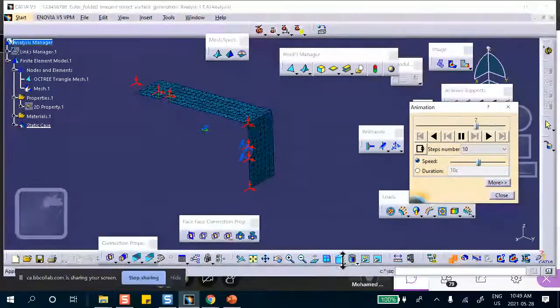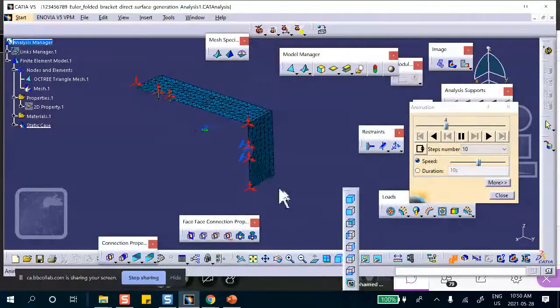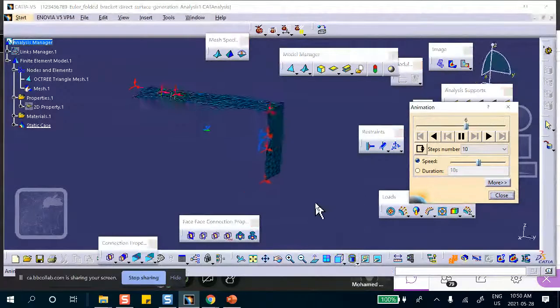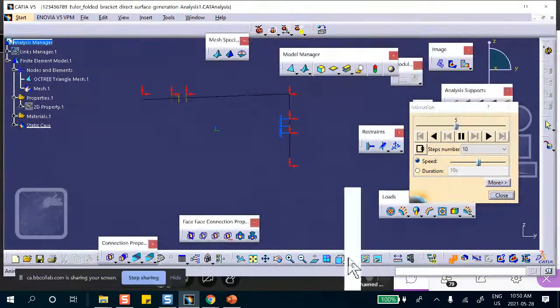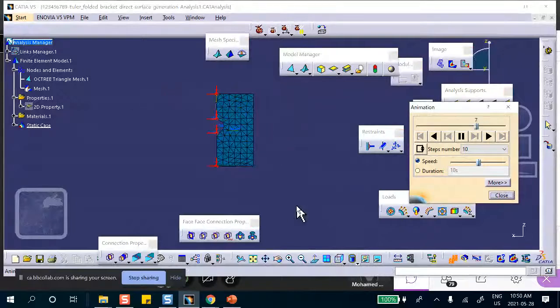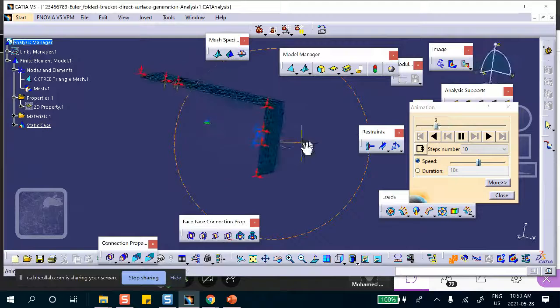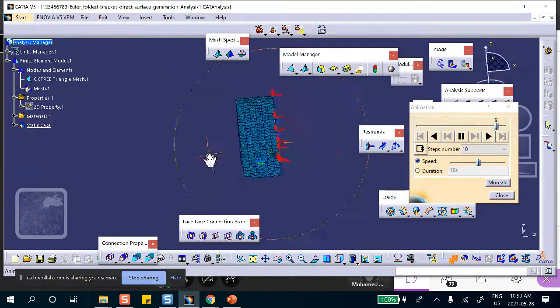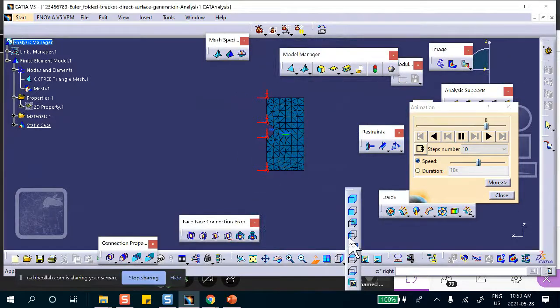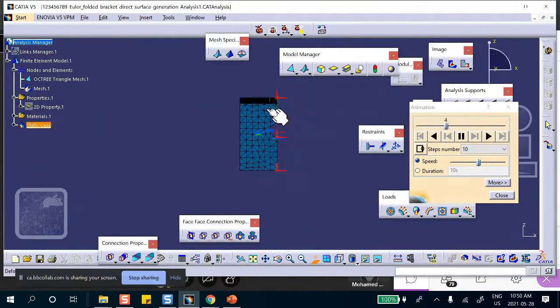Not only that, if you look at the front view, these edges better not go sideways. And not this one. Let's look at the side view, like that. You see? This edge, because of the constraint that you put on it, doesn't go to the left, doesn't go to the right. That's a good sign. This actually is bending. You can see that. Let me turn it around. Oh, no, I want the other side then. Okay, like that. Very good. See, it is bending, but it doesn't go to the side. It shouldn't, if there's symmetry involved here.